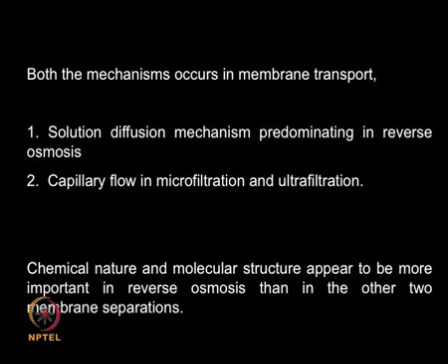Very simple. If you look at reverse osmosis, mostly you will have the diffusion mechanism taking place, whereas in microfiltration or ultrafiltration, you will have capillary flow taking place. The chemical nature and structure of the molecule become important in a diffusion process. So in reverse osmosis, the size of the molecule, the diffusion coefficient of the molecule, and the rate of diffusion all play an important role. In that situation we will use the diffusion model, not the capillary flow model.